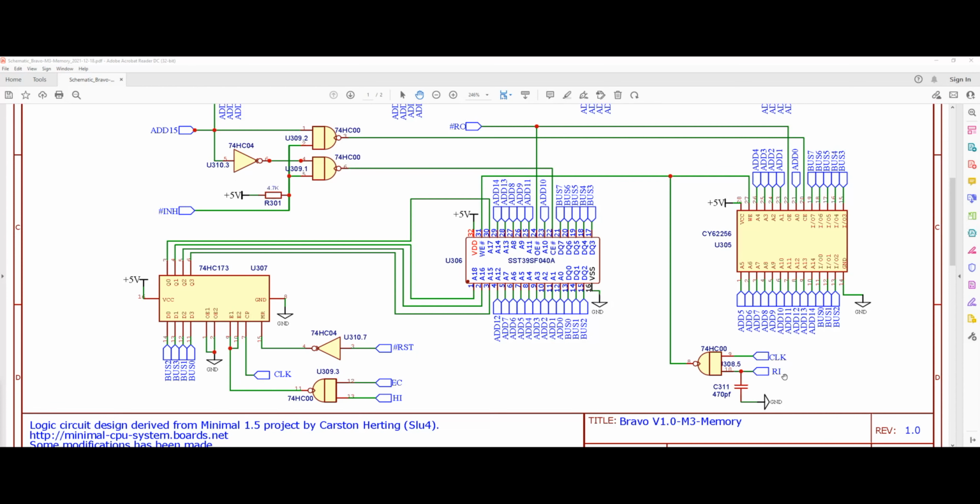And that's why here you see that the RAM signal actually comes to a capacitor, and whenever you bring that RAM in signal high, for the duration of the time that the capacitor is charging here, the signal will be high, and then it's going to go low. And again, it's really all about timing and how long you want that signal to be high here. Again, using a 470 picofarad capacitor here, we are able to actually match the timing for our write operation here. And that's really all about it.